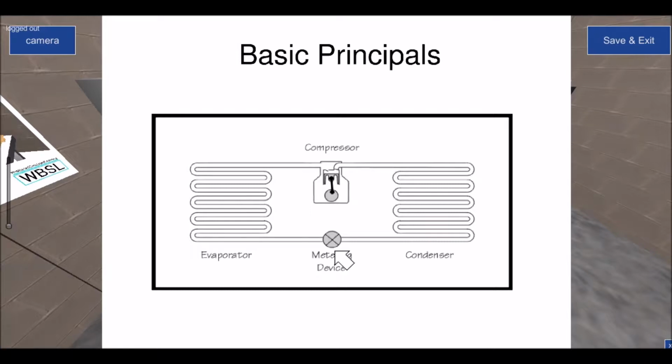And this is often referred to as adiabatic expansion, whereby you've got instantaneous boiling off of liquid, and the temperature stays within the energy, or within the body of the fluid itself, so in this case the refrigerant, and that temperature isn't given off to the surrounding body. So in other words, the valve itself doesn't drop in temperature. So the refrigerant itself will go from a high pressure, high temperature liquid to a low pressure, low temperature liquid, and there will be a small amount of vapor.